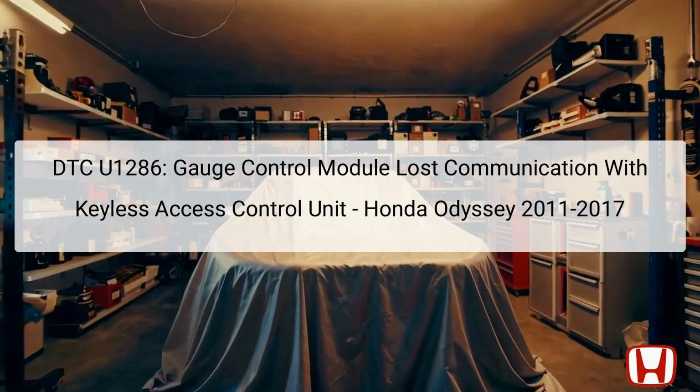The DTC U1286 code indicates that there is a communication issue between the gauge control module and the keyless access control unit in the Honda Odyssey models from 2011 to 2017. This communication is crucial for the vehicle's functionality, especially concerning access and ignition systems. The gauge control module is responsible for displaying instrumental data on the dashboard, while the keyless access control unit allows for keyless entry and starting of the vehicle.